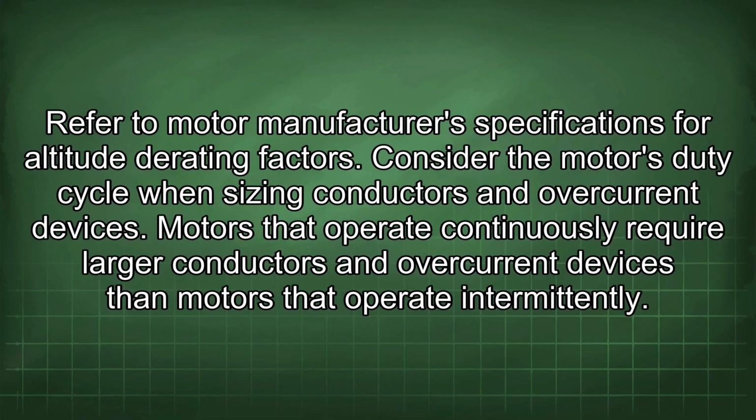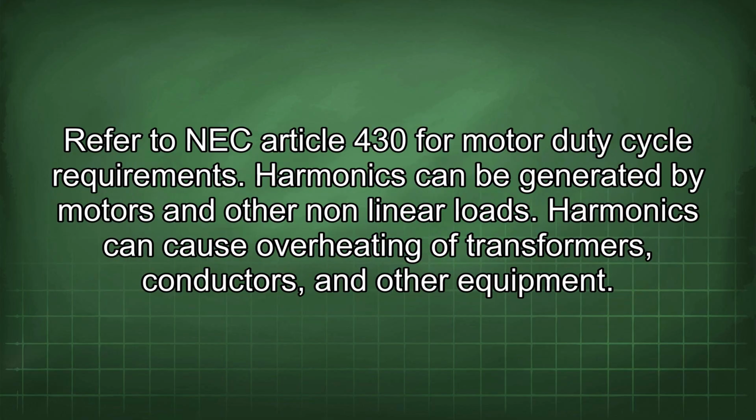Consider the motor's duty cycle when sizing conductors and overcurrent devices. Motors that operate continuously require larger conductors and overcurrent devices than motors that operate intermittently. Refer to NEC Article 430 for motor duty cycle requirements. Harmonics can be generated by motors and other nonlinear loads.